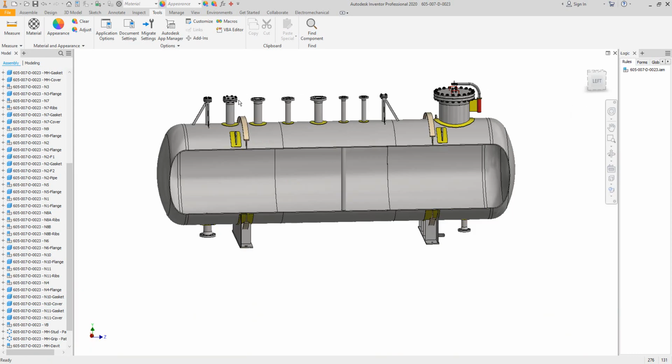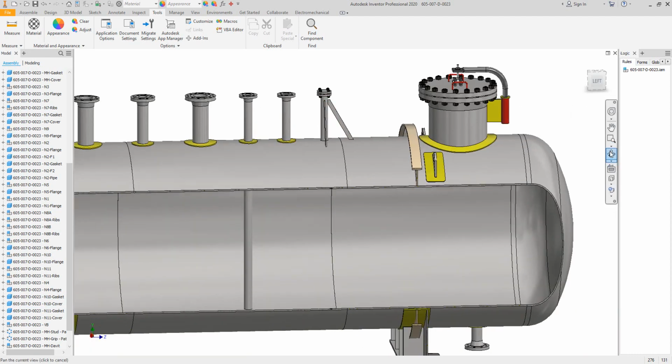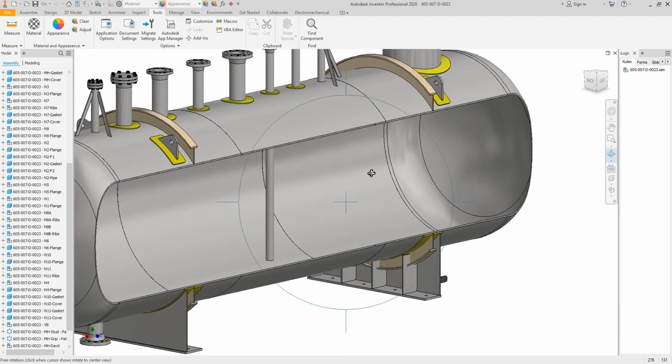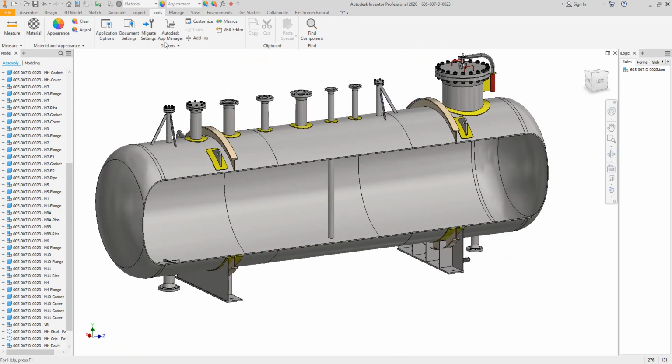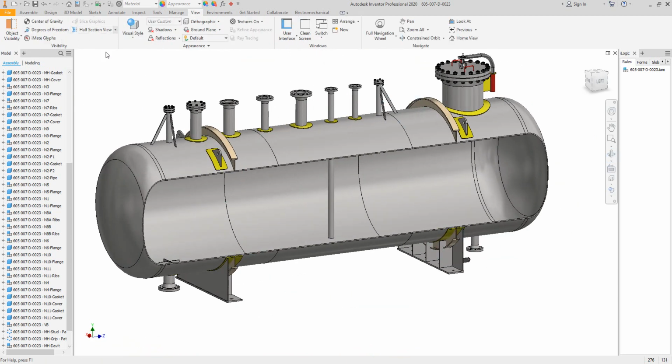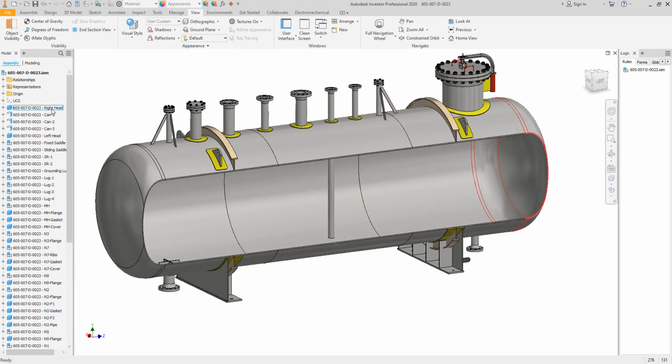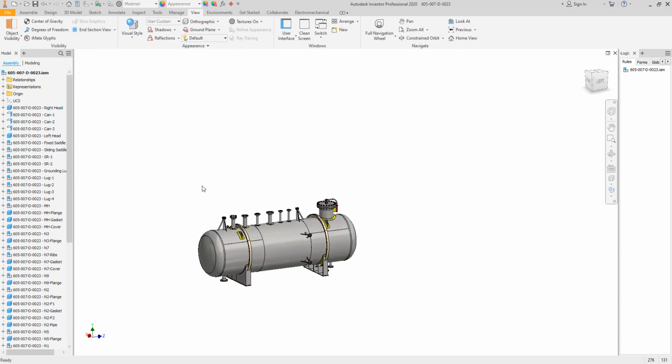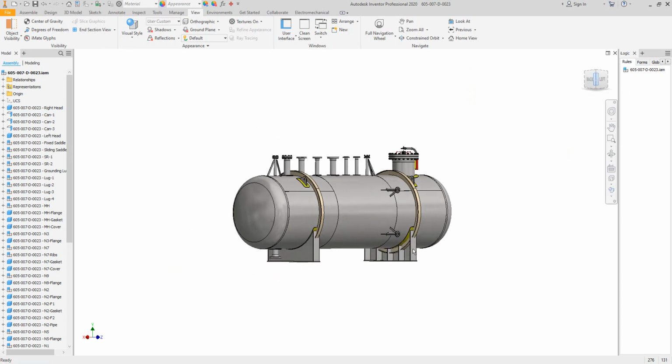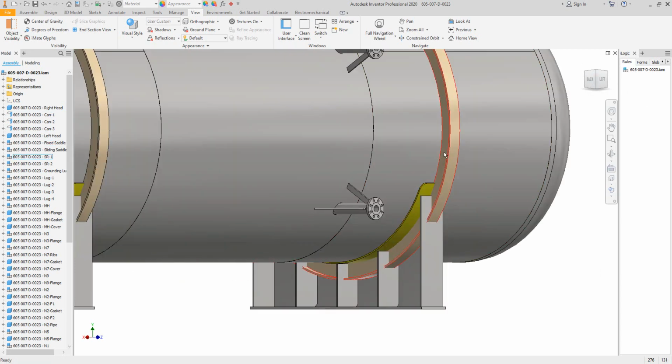Okay, now we have created the stud bolts for all the model. Now we need to make a cut on the width of the stiffening ring, and now we will learn how to make that. Okay, now let's go to the level of the part from the assembly model.